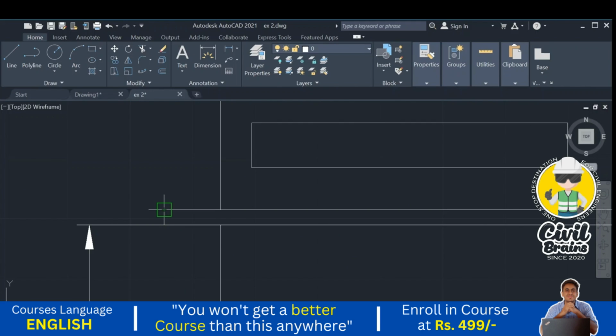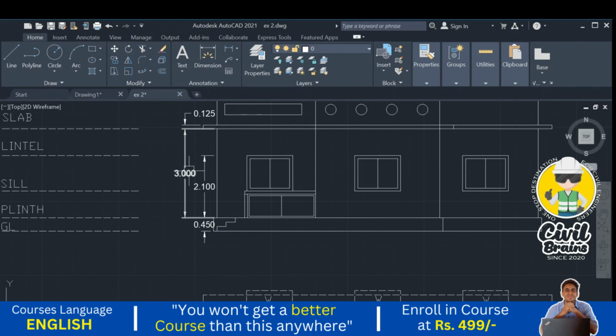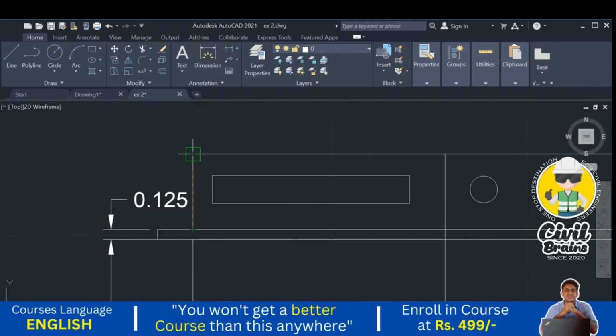Thickness of the slab 0.125, it is 125, right? Dim style, I just go modify text height, I just changed so that it will be visible properly, and primary units I just keep it as 0.125. Okay, close, correct. And parapet height, this is our parapet height.